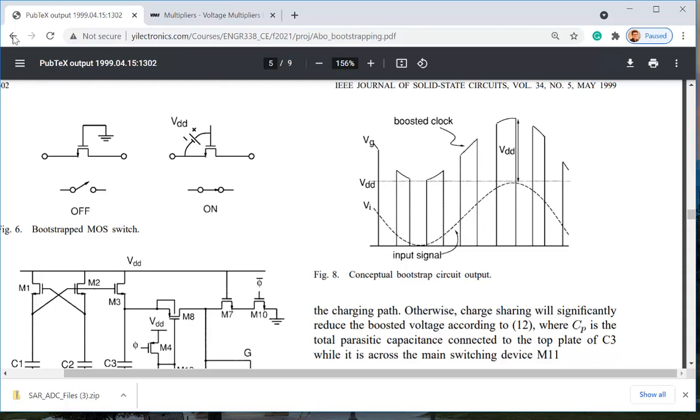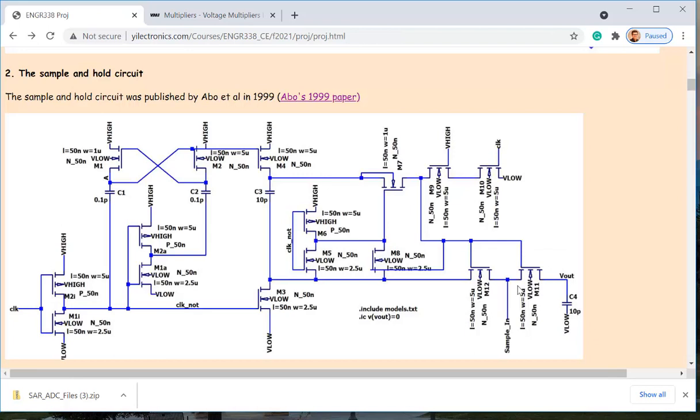All right. So the reason we want to do that is for the last stage over here, we're going to keep the VGS constant as a pass gate. We don't want to change it, because you can imagine, if we just connect the gate of this stage on, because this is the last stage, whenever the voltage in changes, VGS changes.